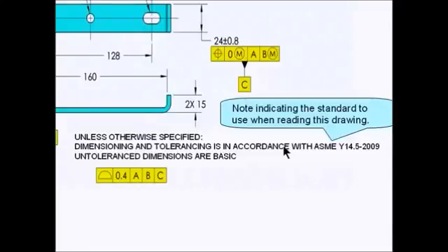You know, if I watch a movie based on the life of somebody, I know there's a lot of fiction in there. So saying you're in accordance with just seems to be a little cleaner. If you want your drawings to have one clear meaning, make certain that it's clear what rules apply. There are no GD&T police that will arrest you for applying an illegal callout, but there are rules that may be contractually binding when a standard is referenced. Here at Techies, GD&T rules.